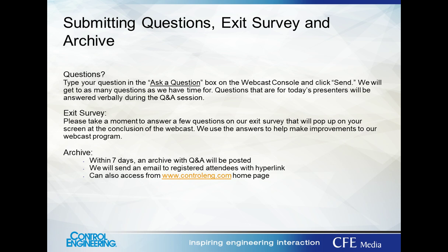Hang on, I'm going to say something more about this. Let me think about it. I guess this is it. A lot of times, what I like to say about feed-forward is that if you're missing a feed-forward signal, it'll find you. You don't have to find it. If you've got a disturbance that's really kicking your stuff in a process, and you look at it, you're going to understand feed-forward pretty quickly and what you need to do to implement it.